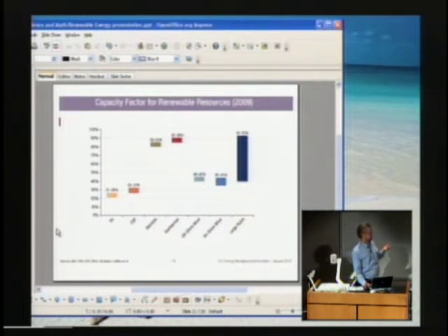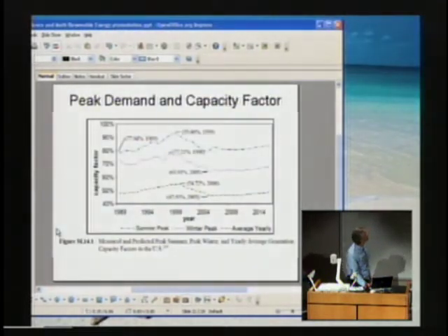To have, say, 20 kilowatts of solar panels, you also have to ask how much of the time they are actually putting out 20 kilowatts, or some fraction of that. That is what the capacity factor is. And if you're going to use so many kilowatt hours, you have to make sure that you have that much. If you don't have another backup source, you have to make sure you can store that much too.